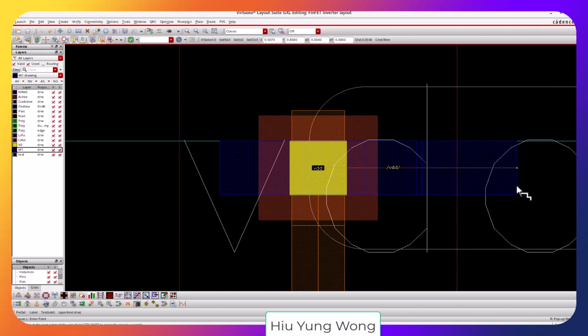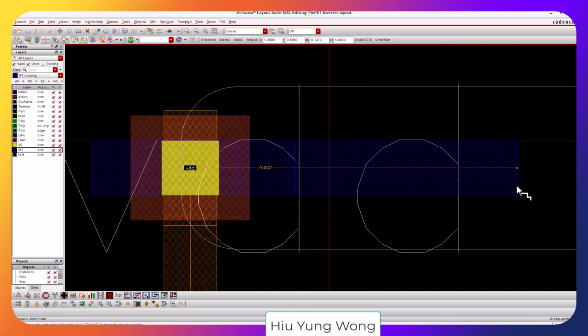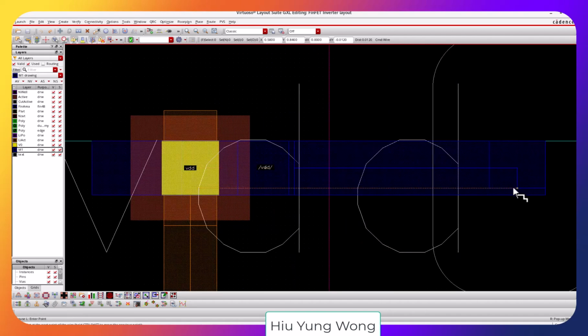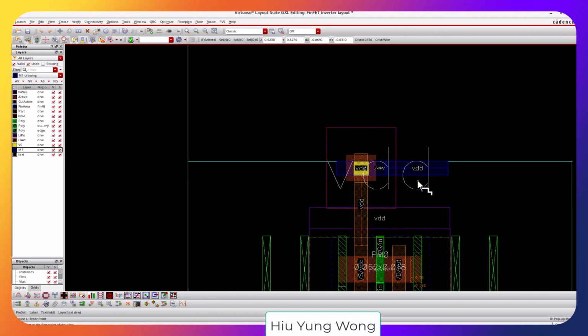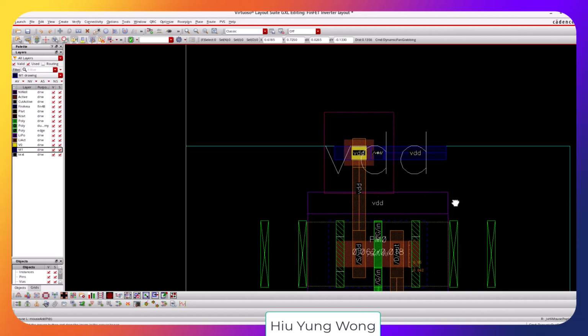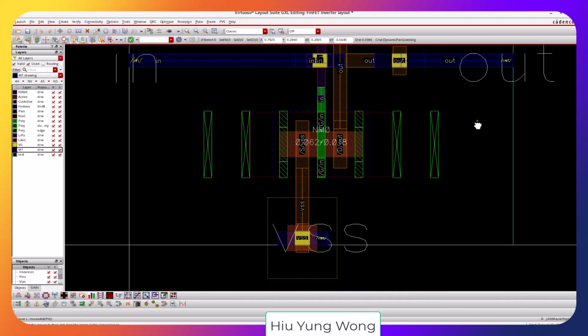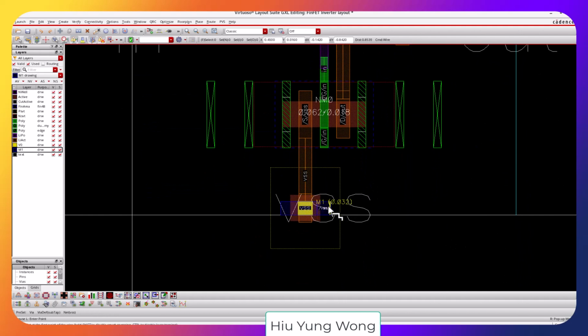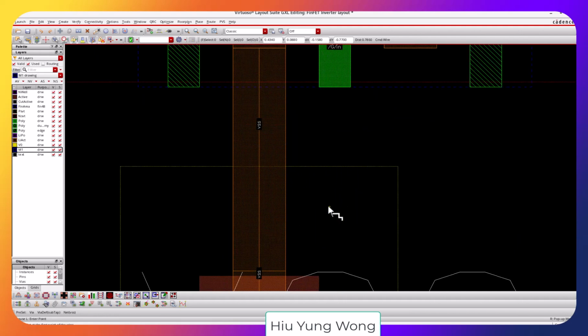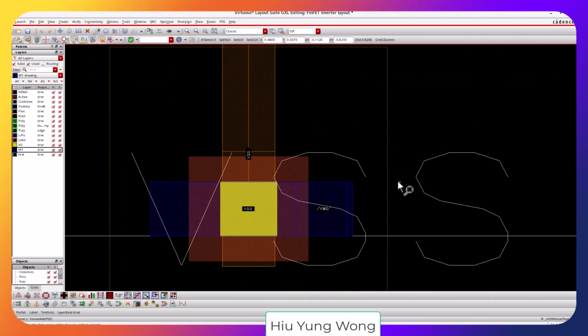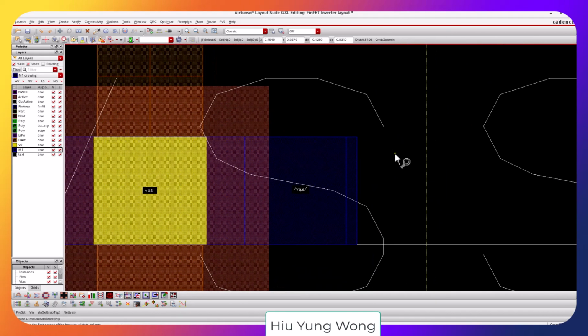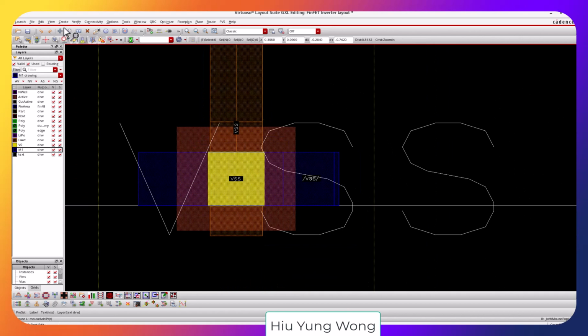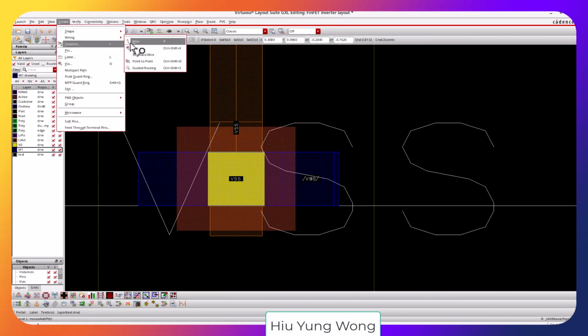Right, so when I'm extending, I can click on the arrow key to go to the right. Okay. Double click, then I have this, right? Again, I use the scroll button to zoom out, and then I can use the middle button or the scroll button, press it down, and then drag out, right? And I have the same problem for the bottom metal, right? And then use Control Z to zoom in, scroll button to drag up, Control Z, drag out, maybe Shift Z to zoom out, right? And then I continue to create wire, right?